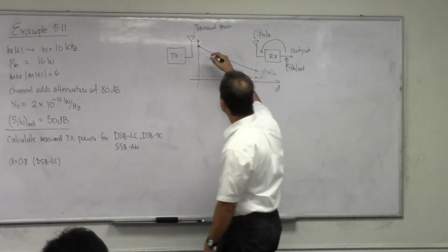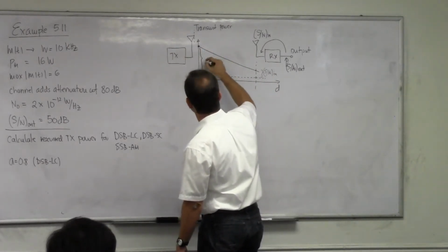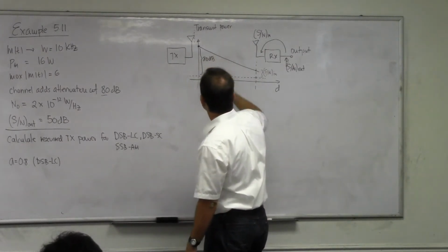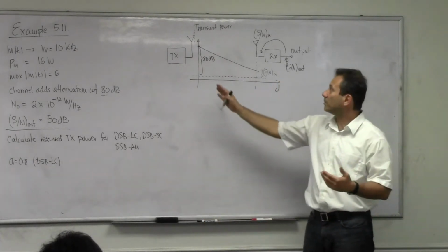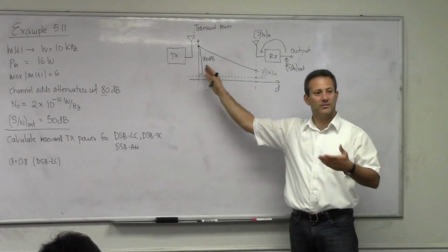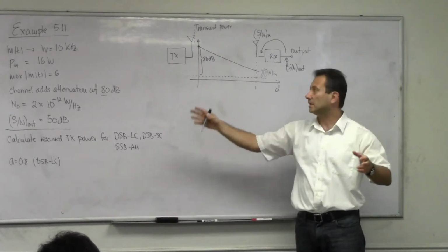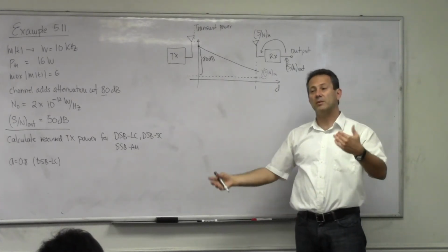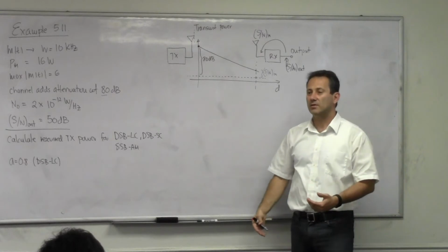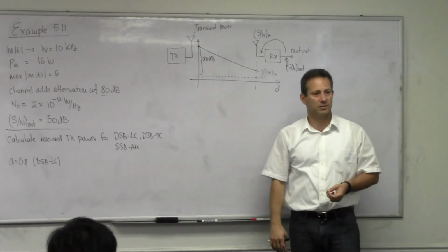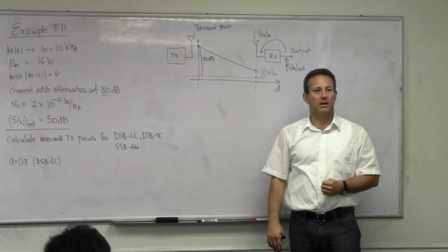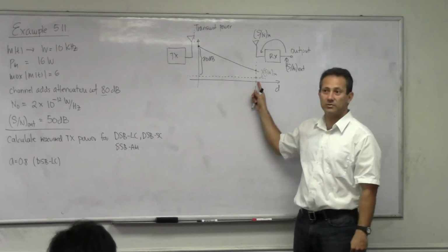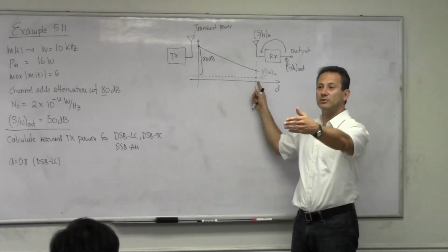Now, this attenuation here is the property of the channel. In my case, this is given as 82. Although I formulated the problem in a logical sense from left to right, where I'm transmitting and wondering how far I can go before I receive, usually the problem is posed to us differently. They want to say, okay, I want you to put the radio station on this tower, and I want you to cover all the way to Orlando, right? So then you start by drawing a circle and say, okay, I need to be able to get there.